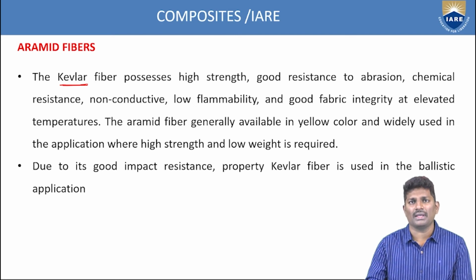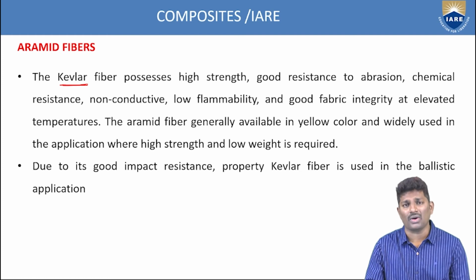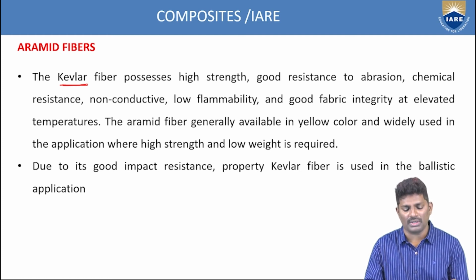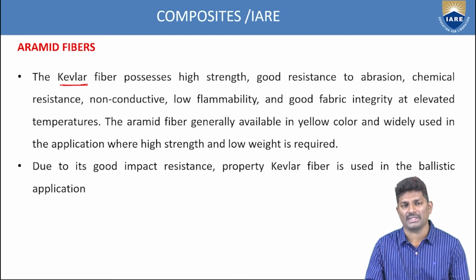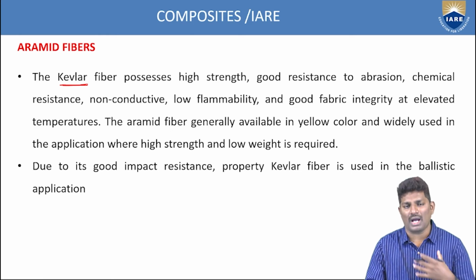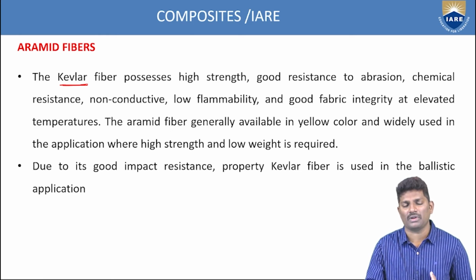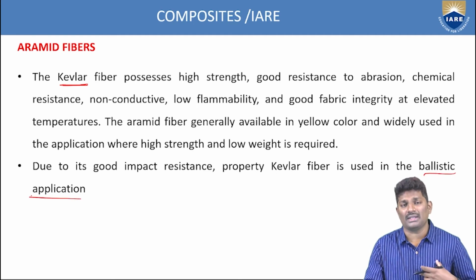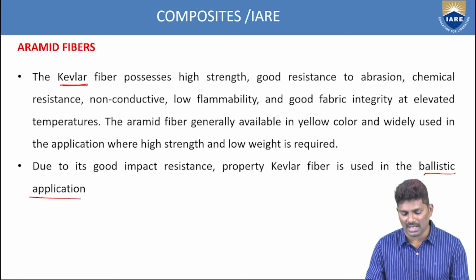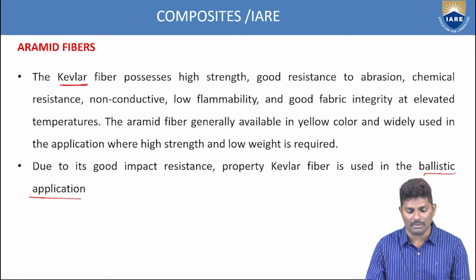So this is one type of composite fiber which has good impact resistance, and it is also used for ballistic applications, where huge impact loads are applied. The military people wear armor, and these armors can be made with these types of Aramid fibers. That's why it is used in ballistic applications, because it is resistant to very high impacts on the body.